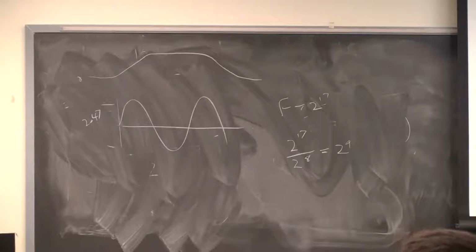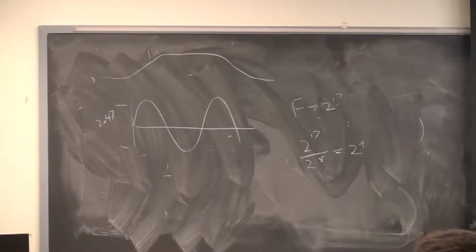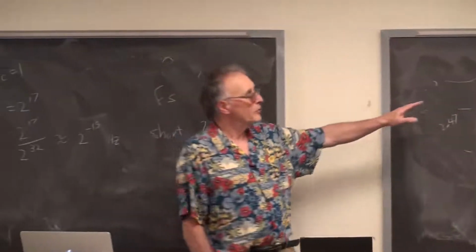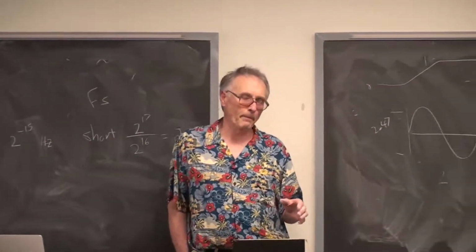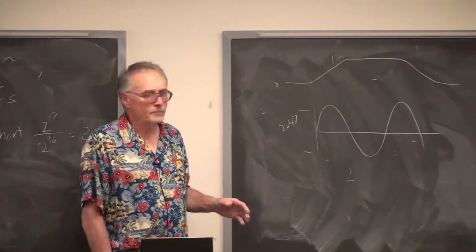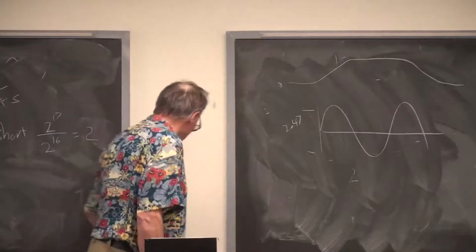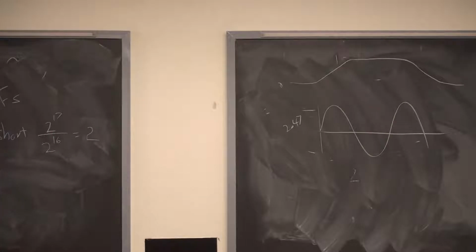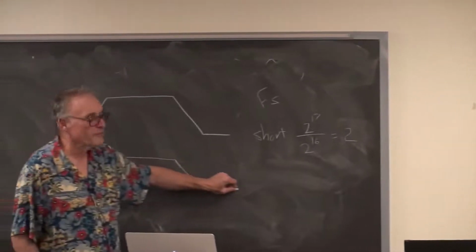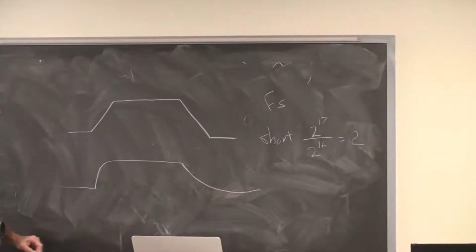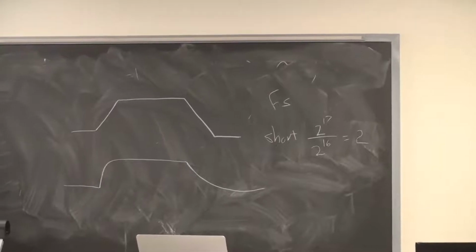So I'm going to want you to program up direct digital synthesis, take the sine wave values, scale them by an envelope, and output them to the DAC. What shape should the envelope actually be? You could ramp the amplitude up, ramp it down. You could use an exponential rise and an exponential fall. You could use a Hanning window.